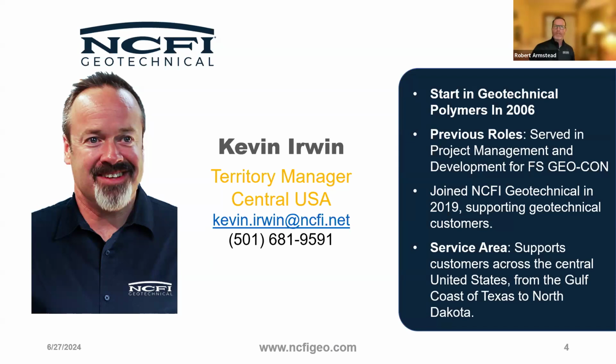Yeah, and I guess the question was really relating to foam density. Their concern was that they're not using a high enough foam density. I'm not sure if it was around whether deep injection was an appropriate approach or not. At the core, I've seen stairs be lifted utilizing just injection right underneath, right? But when you have problematic soils at depth, utilizing a deep injection in that instance would make a lot of sense, right? Because you're doing stabilization at depth.